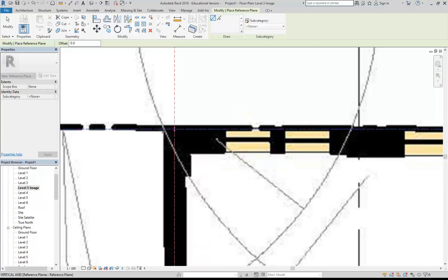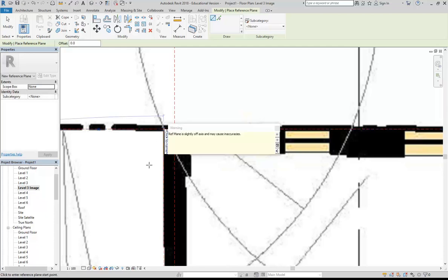So to force it to snap to that angle, one way is to type SN on the keyboard, that's snap to nearest, and that will snap to any point then that I choose. And that's really important, otherwise you're going to end up with everything snapping back to those angles. And here we go. See, it's even telling us it doesn't like these angles, but we need to use it.